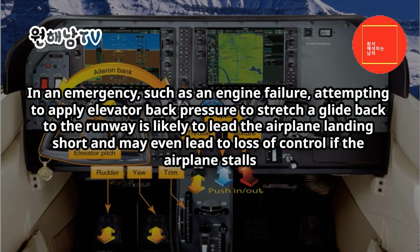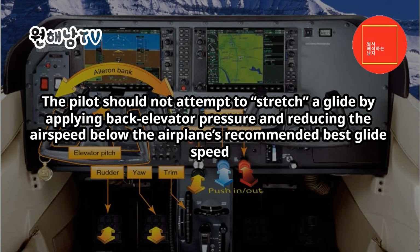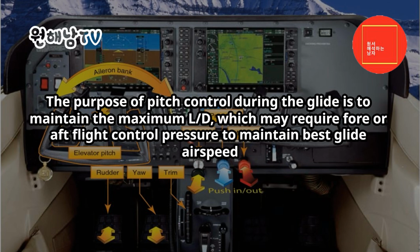In an emergency, such as an engine failure, attempting to apply elevator back pressure to stretch a glide back to the runway is likely to leave the airplane landing short and may even lead to loss of control if the airplane stalls. This leads to a cardinal rule of airplane flying. The pilot should not attempt to stretch a glide by applying back elevator pressure and reducing the airspeed below the airplane's recommended best glide speed. The purpose of pitch control during the glide is to maintain the maximum L/D, which may require fore or aft flight control pressure to maintain best glide airspeed.